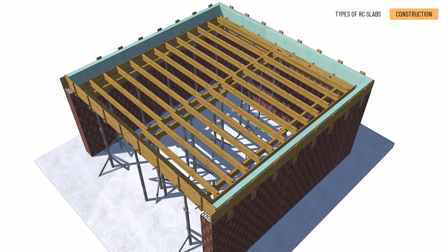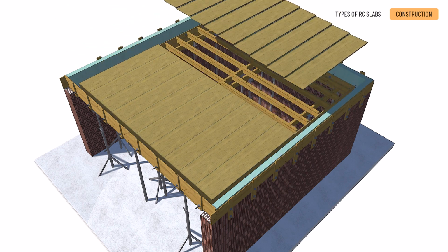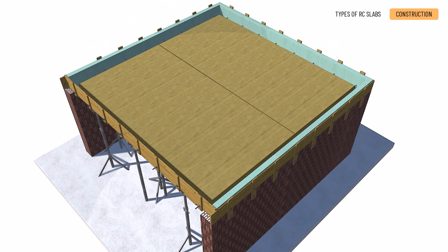Finally, place the formwork sheets. The formwork of the associated structures, such as beams, stairs, and others, is connected to the large slab system, either by using the elements of the same system or by applying a custom-made traditional formwork.